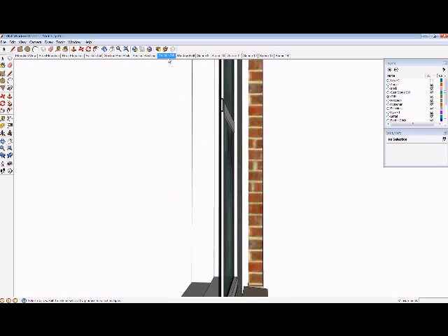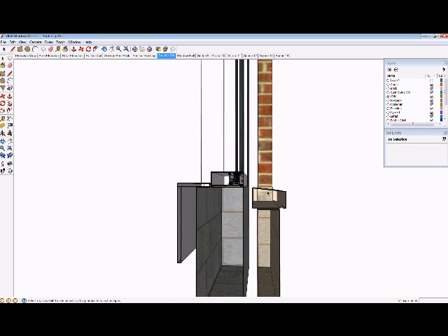We'll look at the lower section here. The detail calls for the precast to return back to the block and for the water to shed off of there. Now there's probably another piece of flashing that was missing in that detail that needs to go over the top to make sure that any water kicks out over that sill.